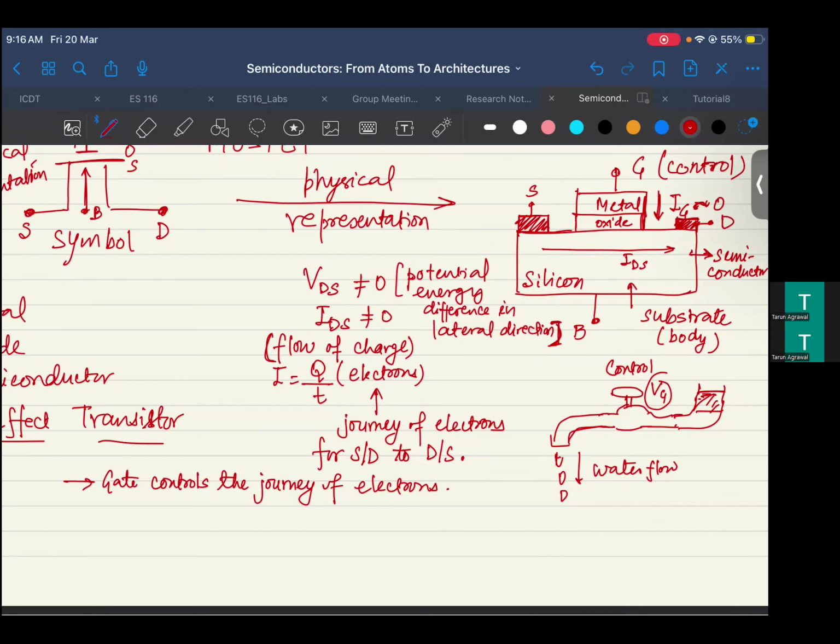That means if I have a gate voltage of 0, which is what we were talking about, IDS is very close to 0. This is what we saw in the functionality of the switch. That is a good switch. And when VGS is some positive, high voltage, let's say plus 5 volt, you have IDS which is finite, or appreciable.